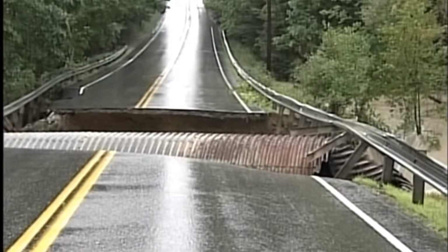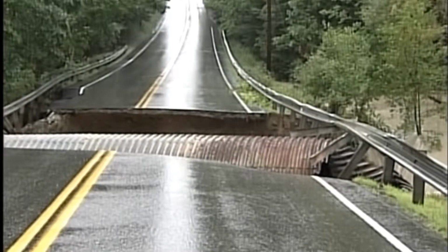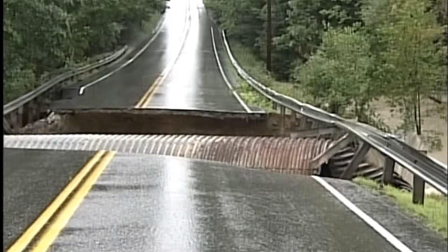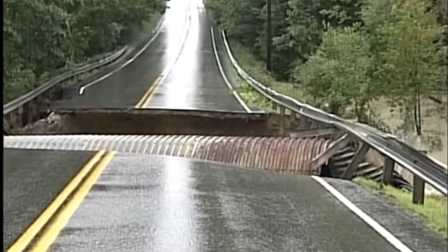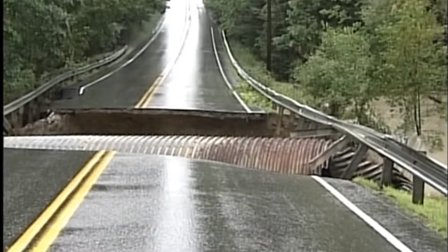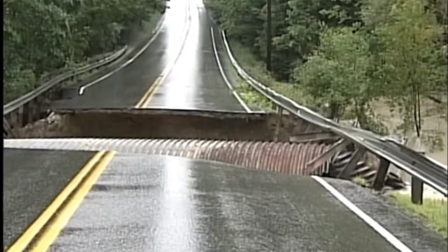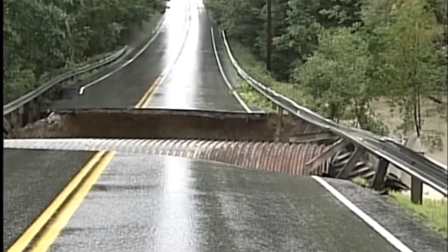In order to prevent catastrophic failures like this, proper soil testing such as Atterberg limits, grain size distribution, and permeability tests are needed to ensure surrounding soil is well graded, has high permeability, and is densely compacted soil to allow drainage around the culvert without erosion while providing structural support.